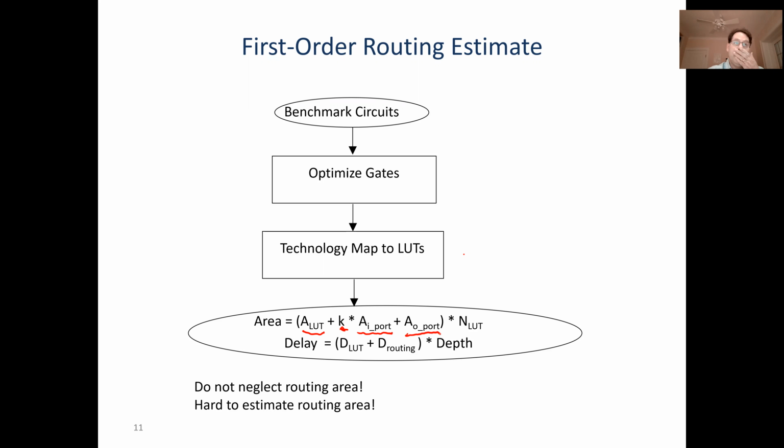So we looked at that last week as well. We looked at a style of routing where we built it on the multiplexers, and we worked out how many multiplexers we needed to build and how big they were. That's the area I'm really going to need for every LUT. It's not just the area of the LUT, it's also the associated routing.